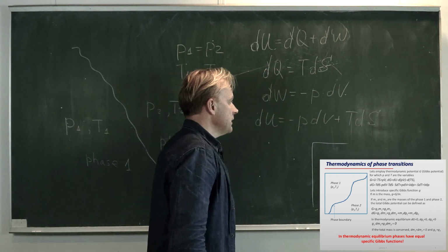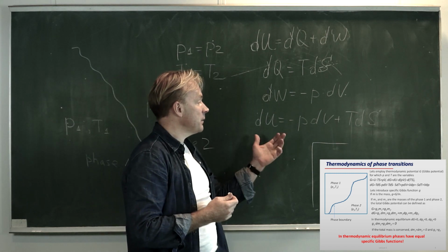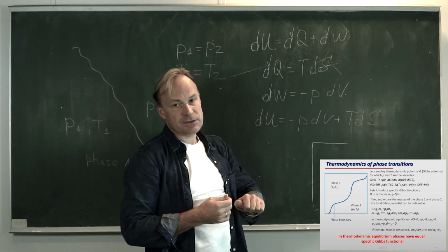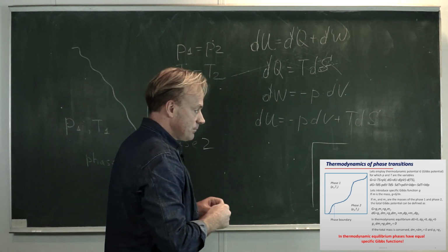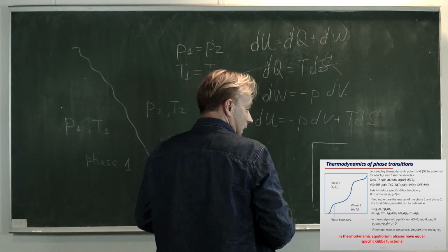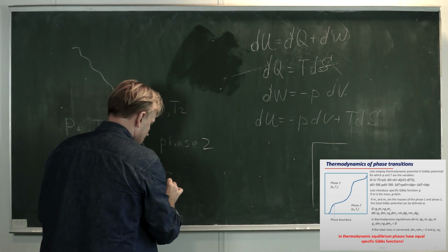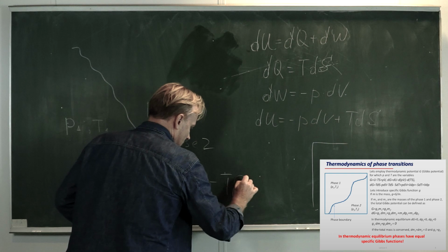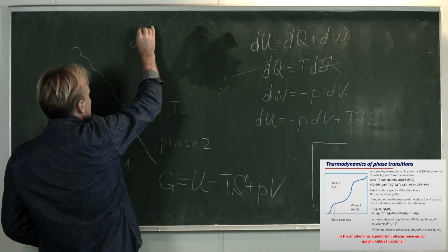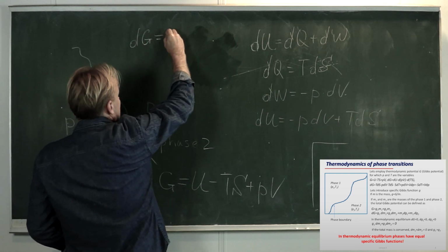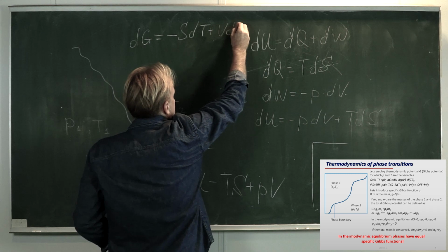that we did already several times during this course, and from where you can see that internal energy is a thermodynamic potential, but the problem with this thermodynamic potential is that it has volume and entropy as variables, and we would like to have a thermodynamic potential for which pressure and temperature are the variables. If you want to derive a potential like this, let's call it G. It is possible if you define the potential in this way, so you can check it yourself, then if you calculate the differential of G, it would be equal to minus S dT plus V dP.